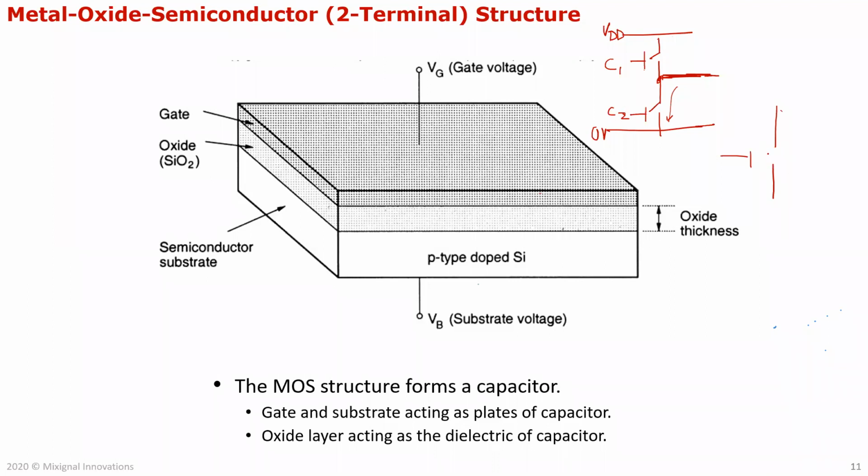So in other words, you can say I'm looking for a voltage controlled resistor actually. So when this control voltage is high or low, whichever way you want to control it, this resistance looks like open, infinite, or it looks close to 0. So when it looks close to 0, the switch is on. When close to infinite, the switch is off.